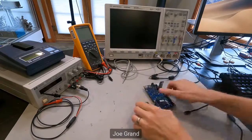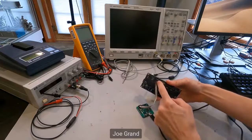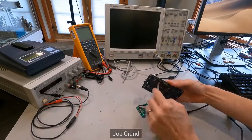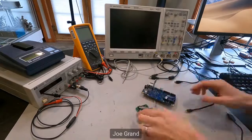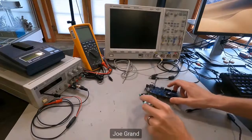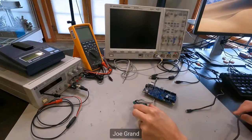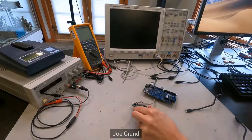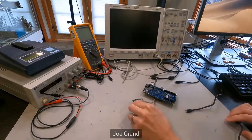And this, we already know what the JTAG pinout is because it has a handy connector that says JTAG, and it's a standard ARM connector here. So if we didn't know, we would use the JTAGulator, find the pinout, and then connect a tool like this one, which is the Tigard, which is a general purpose kind of serial device hacking tool by Joe Fitzpatrick. And this, I believe, is available on Crowd Supply.